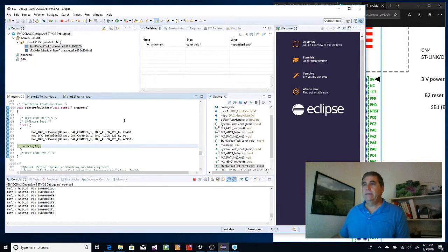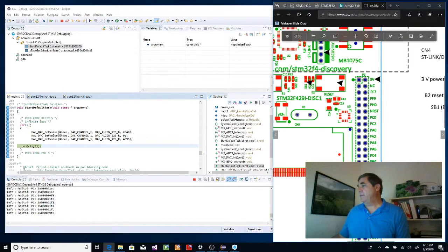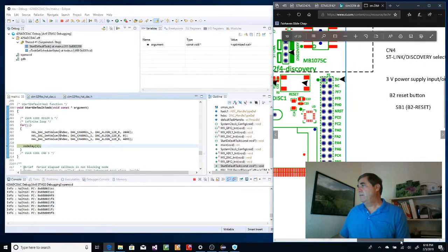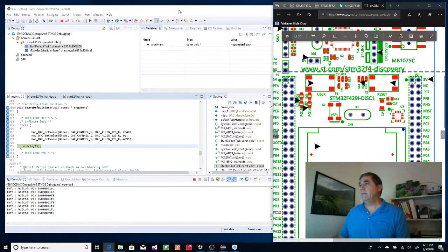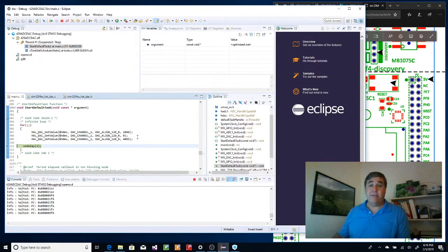Not what I expected. I'm going to run this test again, maybe with a different alignment, because I'm not sure that that's the expectation I would have. And it's close to 3 volts, 2.8, and half was 1.4 and 0, 0, and that's good. Initialized to 0. So it's all the things that I expected it to be, but I'm just sort of wondering if it should be closer to 3.3 volts versus 3. I don't, well, I guess look at this right there, 3 volt power. So the processor is running at 3 volts. Okay, so pretty much, it's just a meter here. I don't have the right load and that kind of stuff, so it is what I expect it to be.